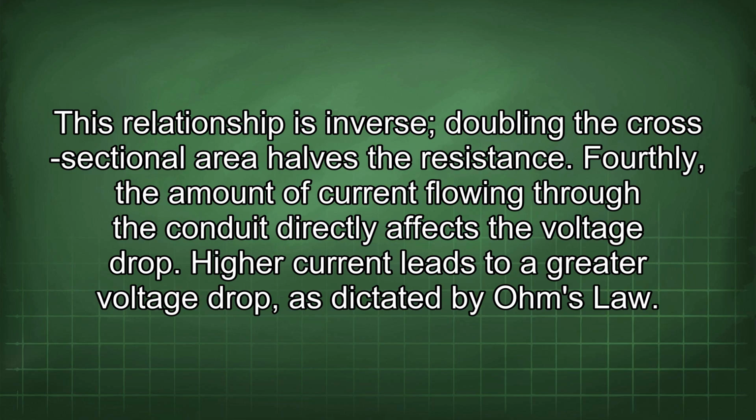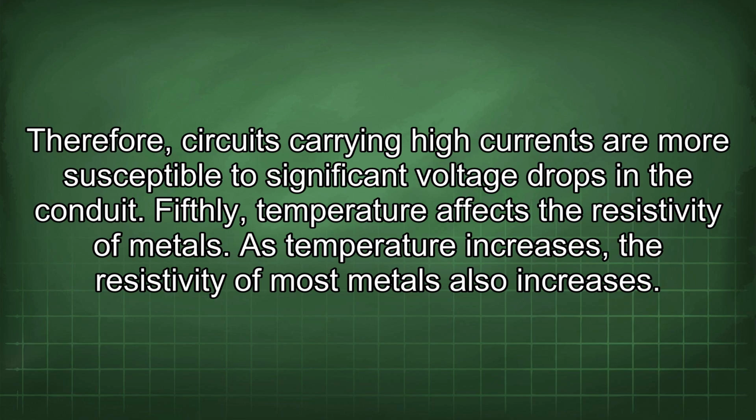Fourthly, the amount of current flowing through the conduit directly affects the voltage drop. Higher current leads to a greater voltage drop, as dictated by Ohm's law. Therefore, circuits carrying high currents are more susceptible to significant voltage drops in the conduit.